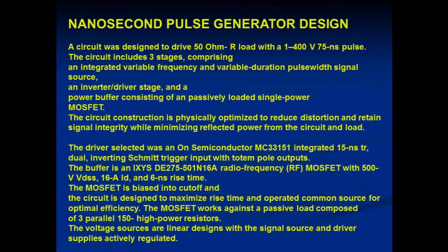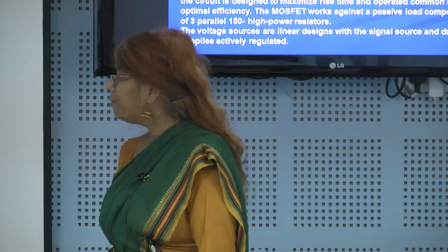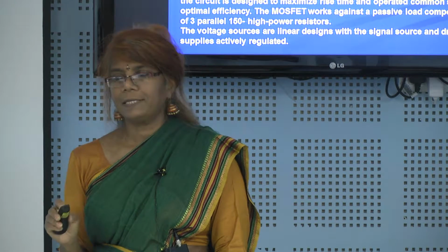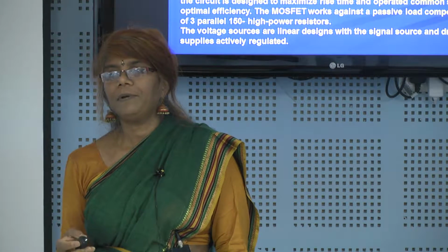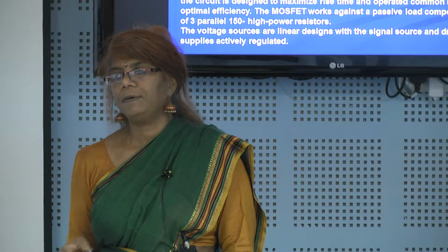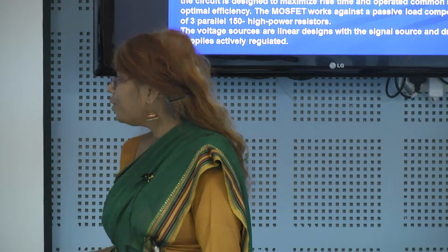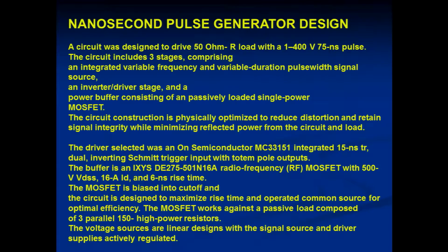And then these are the technicalities, I do not know whether we need them. We need 50 ohm resistors; he did not have a 50 ohm, he had 150 ohm, and he put 3 of them in parallel. Technically that is correct. Practically, what do you think? You have additional connections. So I told him we could have bought one like that, he said no, we do not have time.